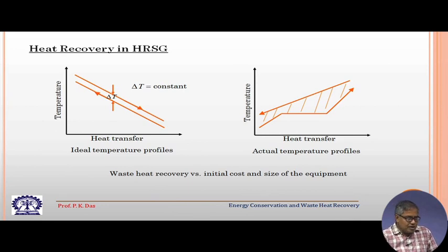In any heat exchanger, there will be two fluids involved for the heat exchange process, and in a counter current heat exchanger, these two fluids are flowing in opposite directions. So, forgetting about the individual heat exchangers inside the HRSG, grossly we can take it as a counter current heat exchanger.